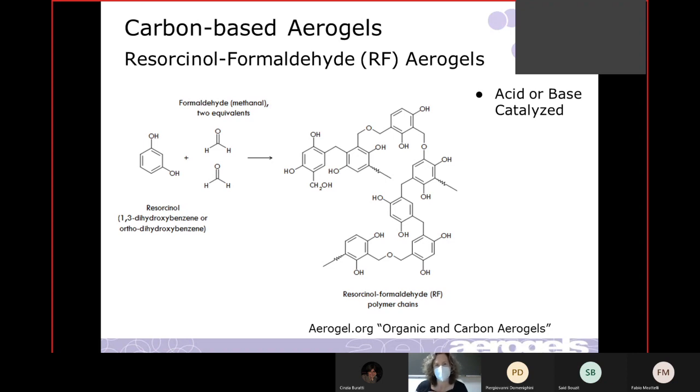And in order to do the rapid supercritical extraction, we have to take the aerogel in the contained mold above the critical point of the solvent that's in the pores. The other reason we haven't done it is because I don't want to work with formaldehyde in the method that we're using and run the risk of having formaldehyde in the exhaust stream.